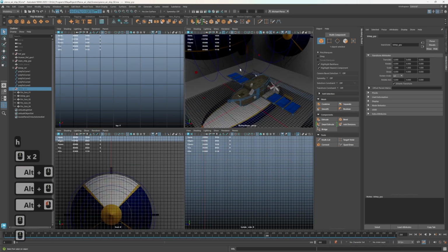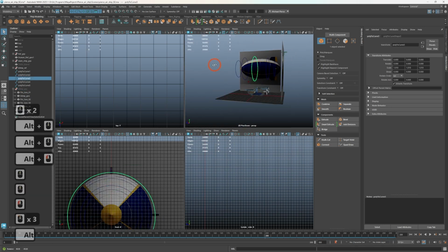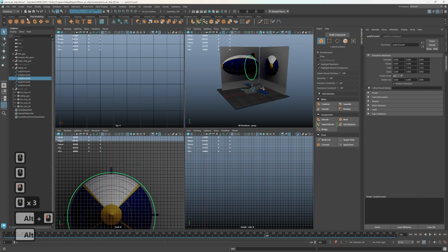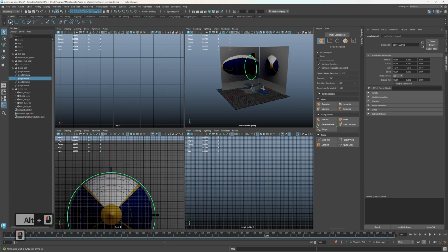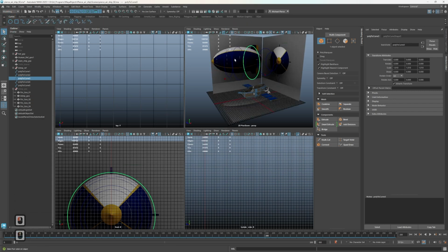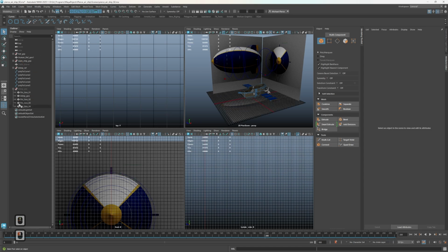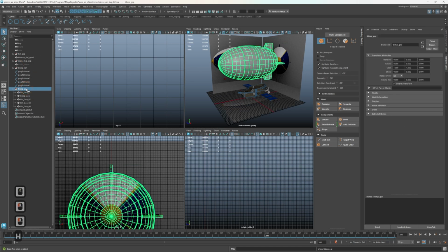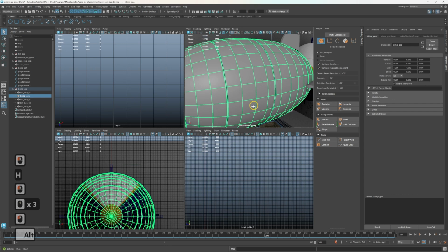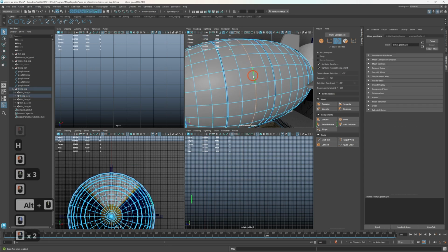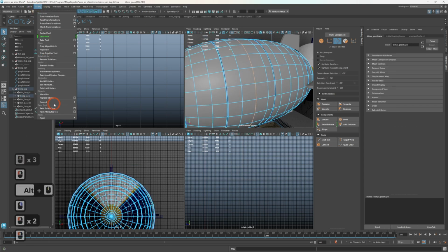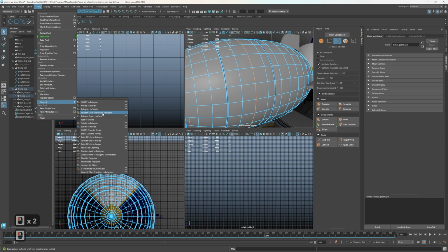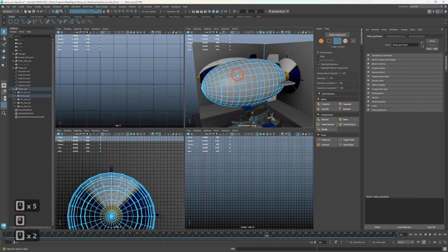Last time we also went along by creating these NURBS curves. So if you go to curves, you can make circles. Well, we got these ones by, if I hit Shift H on this again, right? Very simple, grabbing an edge, going to modify, convert to, and then going from polygon edge to curve, just like that.